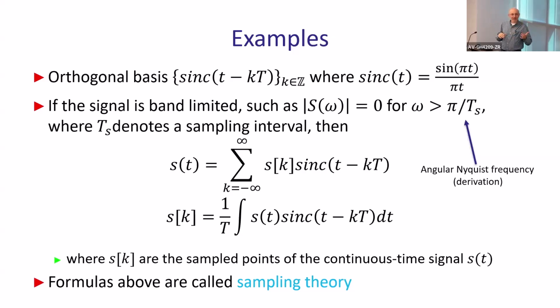Let's say you have a continuous sensor which is measuring some signals, whatever they are. Before you sample that signal and discretize it into a computer list of numbers, you always put a low pass filter with the Nyquist frequency in it to limit the band, so that you will not have aliasing. It's called aliasing of the signal, which means all of the leftovers of higher frequencies will introduce weird artifacts, ringing artifacts, into the signal itself.